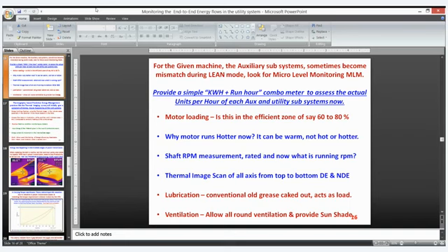This way I was suggesting, whenever the machine or the production is lean or rich, fully loaded or less loaded, you have the auxiliaries with a kWh and run-hour combo meter on all the auxiliaries of your machines, subject to your usage and convenience. This will definitely show if the loading is less than 50% or 40%, there is a heavy loss. If the loading is around 60 to 80%, the energy efficiency for the given motor, right from IE2 to IE3 to IE5, is all excellent.